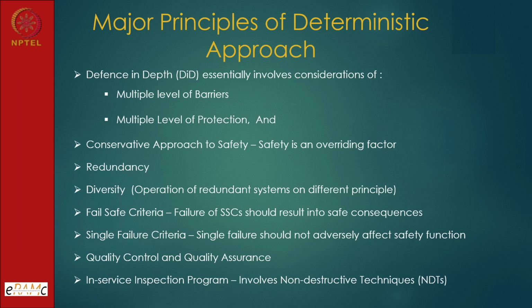So, these two operate on different principles. In one case, we have to open a valve so that all the moderator gets dumped, and in the other case, we have to de-energize the clutch so that all our safety rods are inside the reactor.